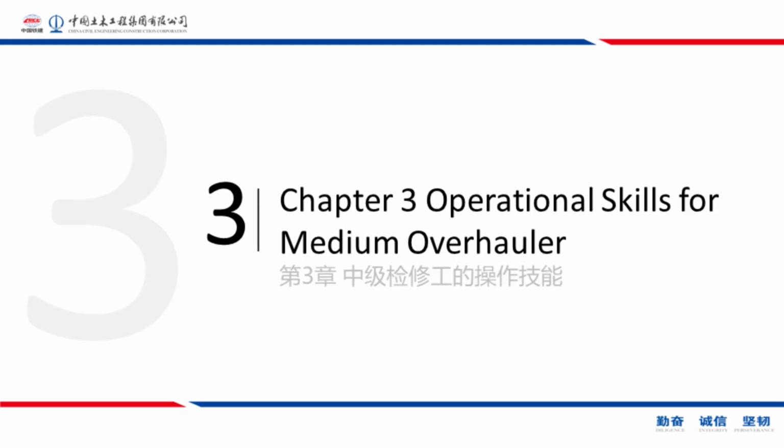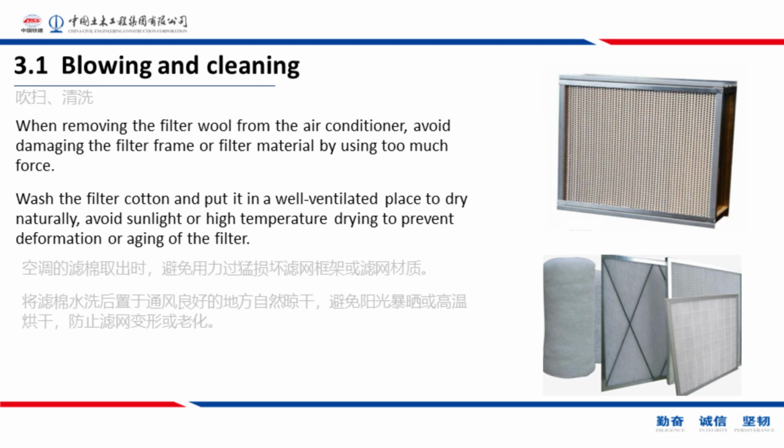PPT 24. Chapter 3 Operational Skills for Medium Overhauler. PPT 25. 3.1 Blowing and cleaning. When removing the filter wool from the air conditioner, avoid damaging the filter frame or filter material by using too much force. Wash the filter cotton and put it in a well-ventilated place to dry naturally. Avoid sunlight or high-temperature drying to prevent deformation or aging of the filter.